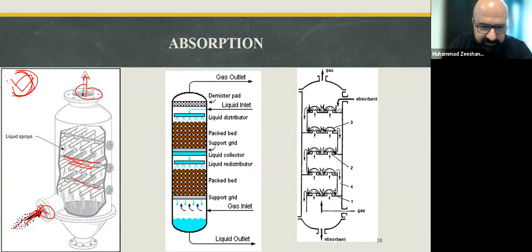But this whole arrangement looks similar, but there are certain differences between the wet scrubber for particulate matter and the absorption column for gaseous pollutant removal. And that difference is normally we don't use water, rather we use specifically designed and manufactured solutions, right, through these showers. Now, what exactly those solutions do is that those solutions have got affinity to absorb a particular pollutant selectively, right? For example, we have got natural gas, which contains a lot of H2S,